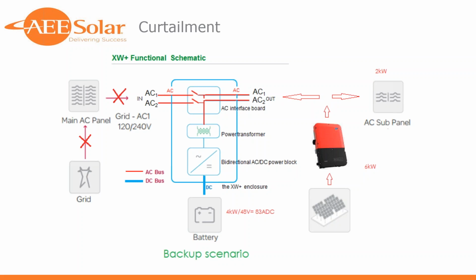Well, the voltage would drop very quickly as loads were being used, and it would try to turn the PV inverter back on, with the PV inverter having to do the 5-minute count up once the grid was qualified. Sometimes there was enough battery to power the loads for those 5 minutes, and sometimes there wasn't.